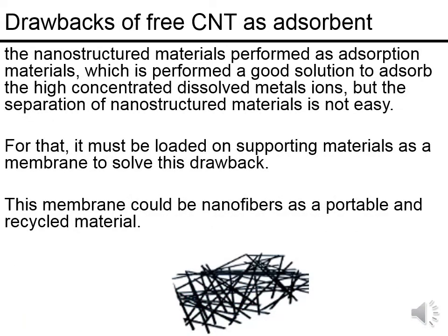But when we think about using carbon nanotubes as an adsorbent, there is a drawback to using free carbon nanotubes. The drawback is how we can dispose of the carbon nanotubes after completing the treatment process, as they will be soluble in the solution. For that, we think to load the carbon nanotubes on a supporting material such as a membrane to solve this drawback. This membrane could be a nanofiber as a portable and recyclable material.